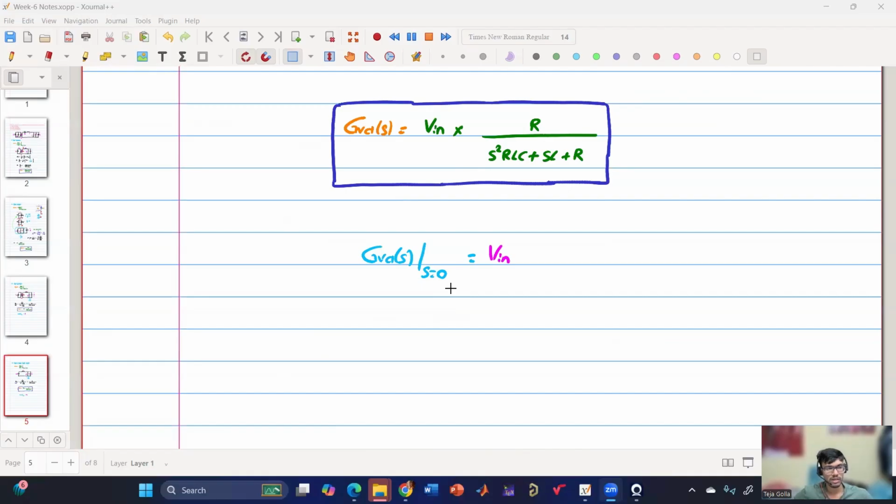Similarly, for a boost converter, we'll get a similar expression, but it has something called RHP zero, so that will come in the numerator. I think Kelvin might have explained. So that's why boost has some additional problems like control challenges, whereas buck doesn't have. Is that clear until this point?